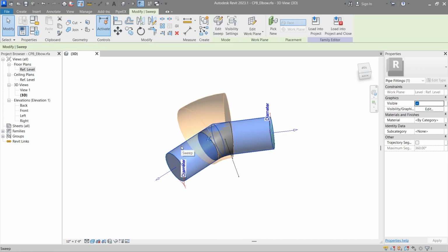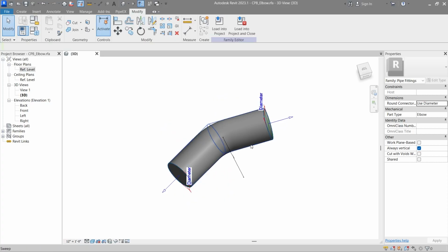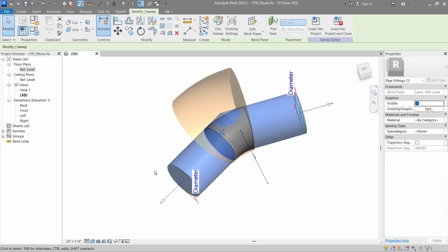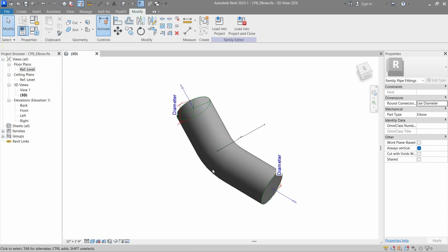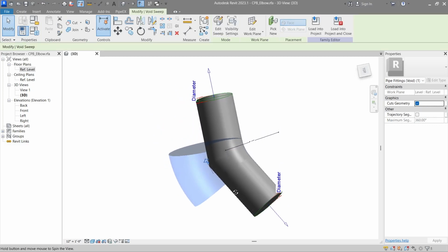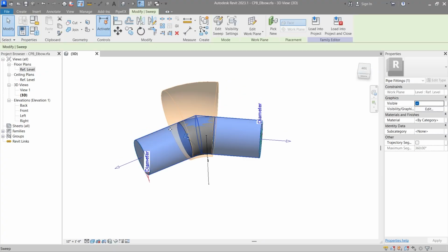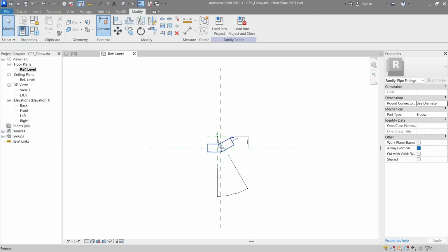The first component was created by a sweep, so we have literally 2 cylinders merged to each other. Then we have a separately created elbow and another elbow to cut unnecessary parts. Why do we need to do that? The thing is, if you try to create a similar kind of shape with only one component, technically you can also do that, but then you will not be able to create the geometry, because I'm going to show you why.